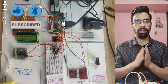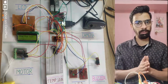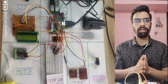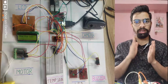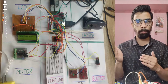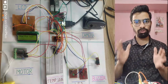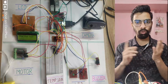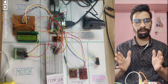Again the third part is, let's say another person comes in front of the camera, then it will detect the person's temperature, and if the temperature is below the threshold level, then it will check the mask. Then the camera will check whether there is a mask or not. If the person is wearing the mask, then automatically the green light will turn on, then the gate will open for some time and the gate will be closed. So this is the complete idea behind this project. Also we can see the status, like gate open, gate closed, on the LCD of the Raspberry Pi. So this is the idea behind this project.